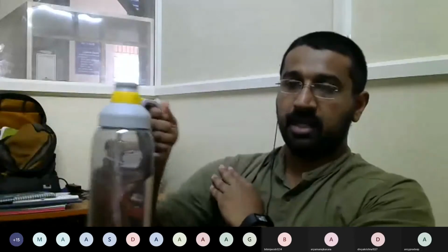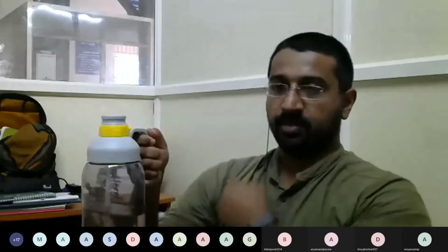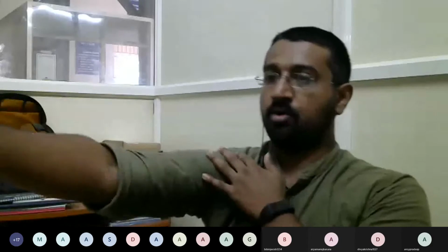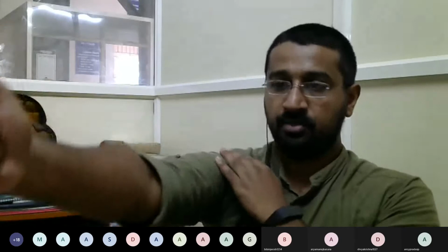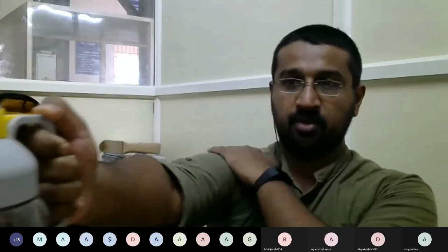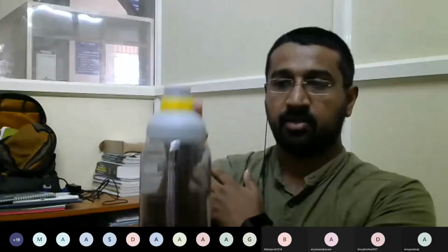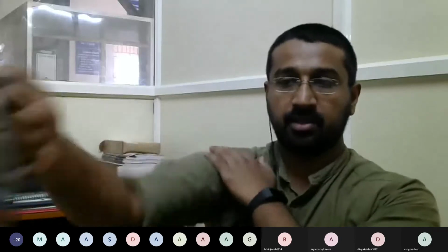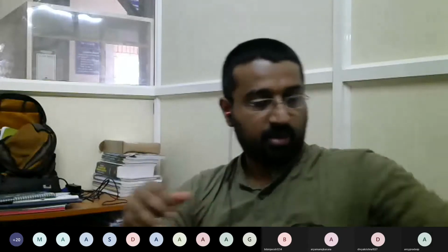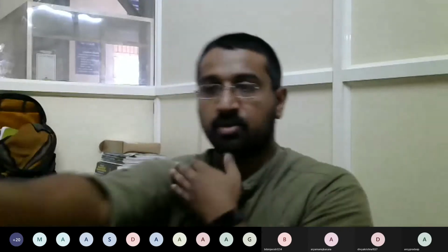Now, if I keep it like this, away from me, still this force into this perpendicular distance, the distance is more and the moment is increasing. How do you know? Pain. If you keep it like this, you're getting a lot of pain. But if I keep it near to me, I'm much relaxed because the moment is reduced. Here the moment is high because the force remains the same and the distance is more. When the distance is reduced, the moment is less. So you should remember that moment greatly depends upon this length, which is also known as the lever arm.